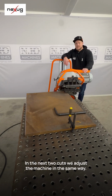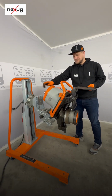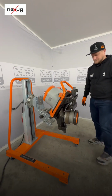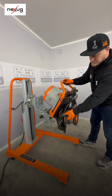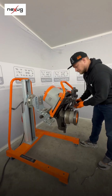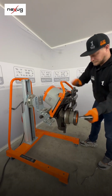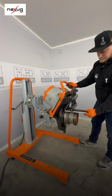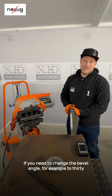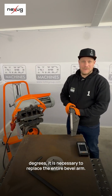In the next 2 cuts, we adjust the machine in the same way. The processing of small sheets is also standard practice indeed. If you need to change the bevel angle, for example, to 30 degrees, it is necessary to replace the entire bevel arm.